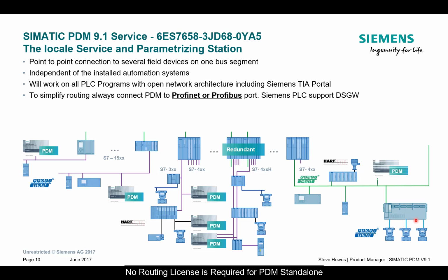So we can have a laptop with a standard Ethernet cable. As long as we've got a spare RJ45 connector on site, we can connect to that, assign your PC an IP address that will work on that network, and then we can start communicating to the devices.